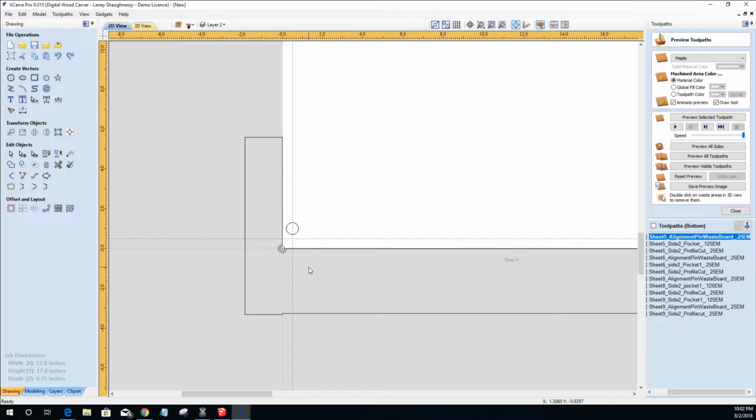But that doesn't mean I can use the same alignment pin holes that I drilled yesterday on a completely different X and Y position, because I could have clamped my board an inch over to the left or down. The jig is just for placement, position on the table.